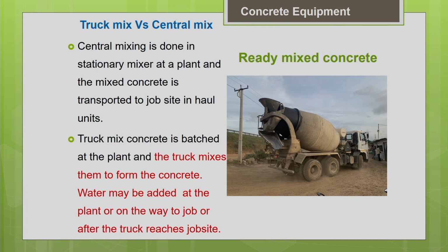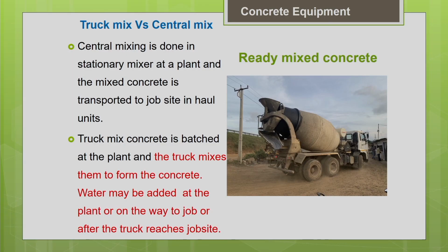So, now we are going to discuss about the ready mix concrete. Nowadays, we are very commonly using the ready mix concrete, particularly for works where the emphasis is more on the quality. We go for the ready mix concrete. So, for ready mix concrete, there are two different ways by which you can make it. I mean, these are the commonly adopted ways. One is truck mix and the other one is central mix.